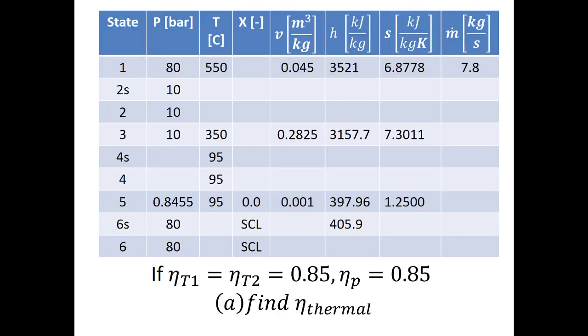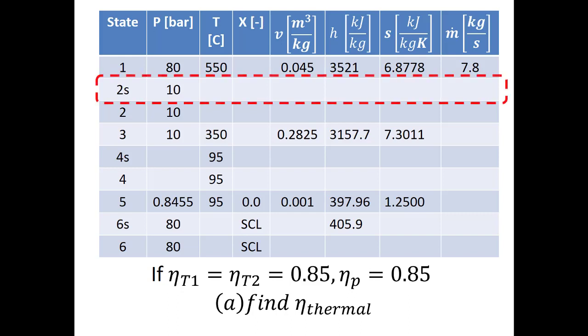So what do I know about the word isentropic? Isentropic is kind of secret code for ideal, but it's only ideal if a process is steady state, adiabatic, and there's no entropy generation. And if that's the case, then from the second law, I can see that across a process like the turbine or the pump, I'm not going to get any change in the specific entropy.